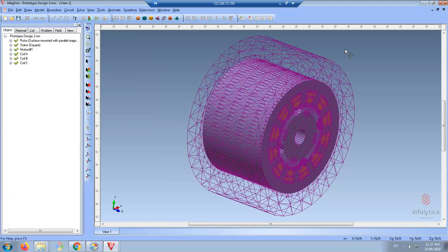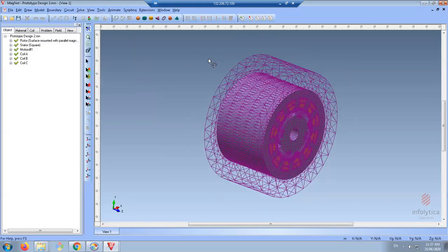It's time consuming, takes too much time. So in symmetric motors, where the motor is symmetric in the z-axis, the structure doesn't change in the z direction. You don't really need to run the model in 3D unless you want to perform a thermal analysis. In that case, end winding effects become really important, meaning that you have to run the model in 3D.